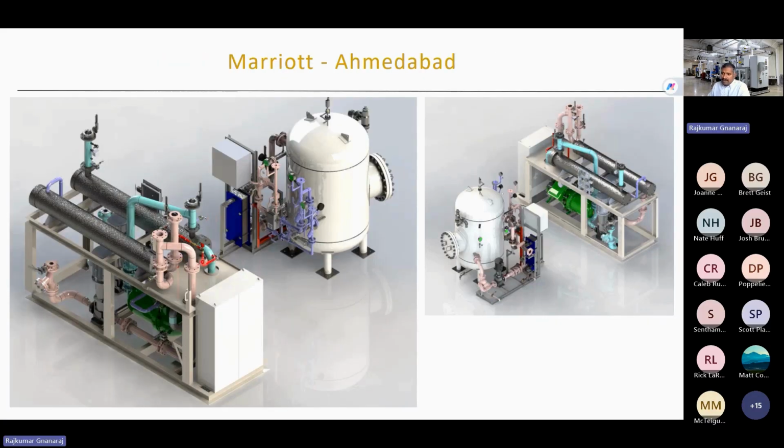So this is the way we have supplied the heat pump systems to the institutional facility, where this is the heat pump with circulation pumps inside, and this is the tank, the three-way valve mixing station, and the secondary heat exchanger, which separates the condenser loop and the water loop from the tank. Typically, we get a very small footprint in a utility room. So we take the dimensions and try to accommodate everything within small packages. So two different packages get supplied to the site, and the contractor takes less time to install it, and they do the commissioning in a very short period of time.